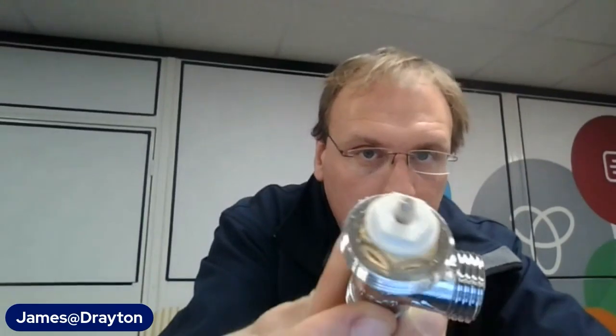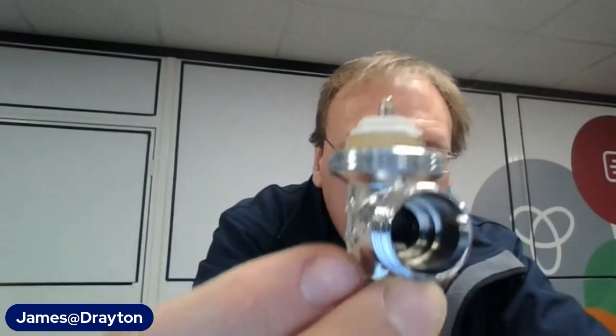So you could say, well, what's the difference between the two? Because they're both liquid sensors now, and they're both EN 215 compliant. So the difference is the bodies that they come with. So the 212, which is our entry level, comes with what we call our fixed flow rate body. So it's very much a contractor's body. There's nothing that you can replace in the top there. There's no replaceable gland seals. There's no way that you can balance on this.